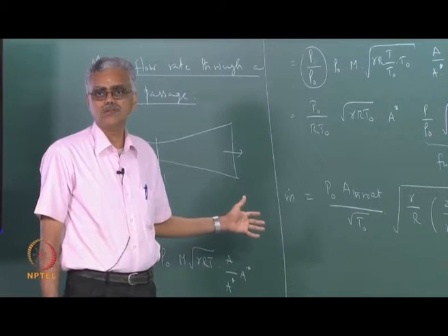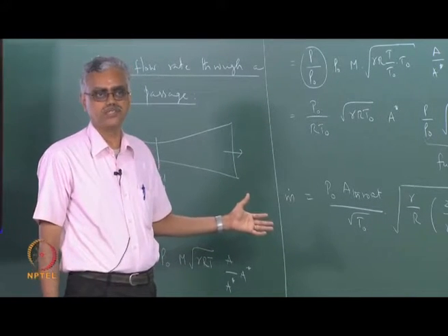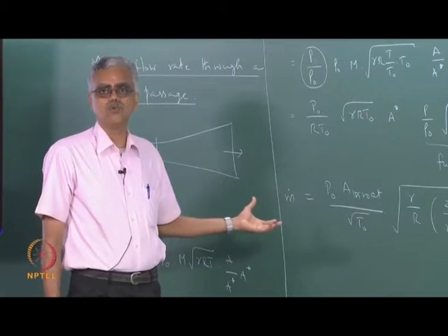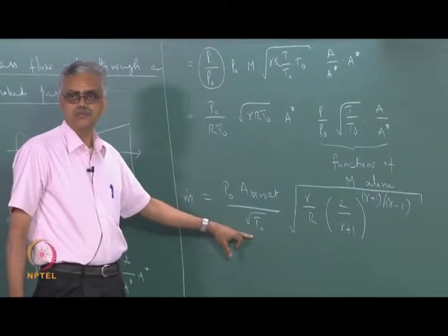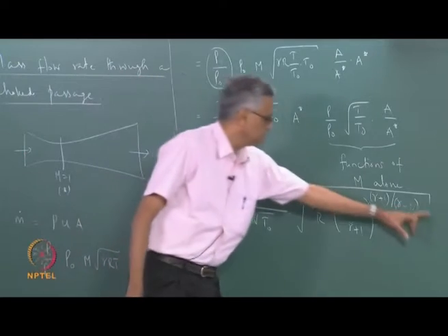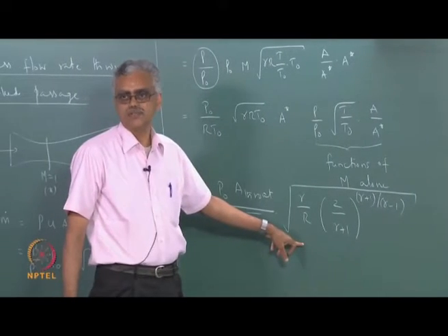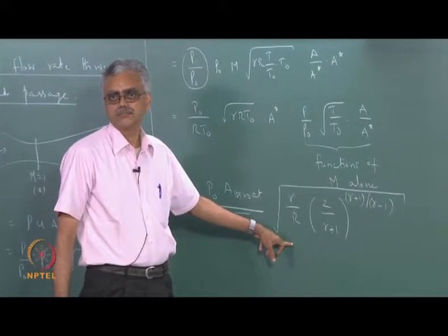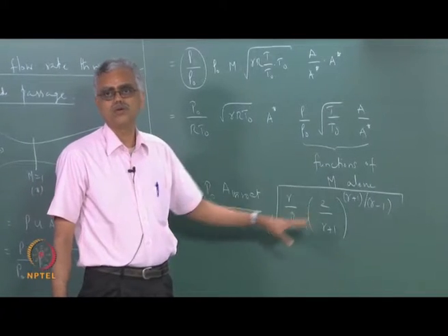The most important or most startling aspect of this expression is that no exit quantities or exit pressure are involved in this, right. This depends only on the upstream stagnation pressure, throat area, and the quantity inside this depends only on the nature of the gas, right. That is the most remarkable thing about this.